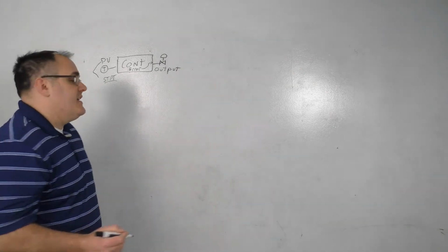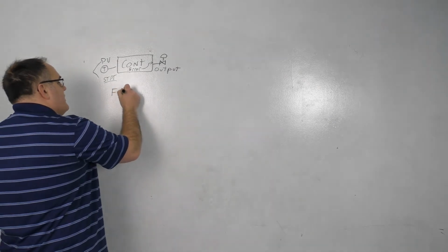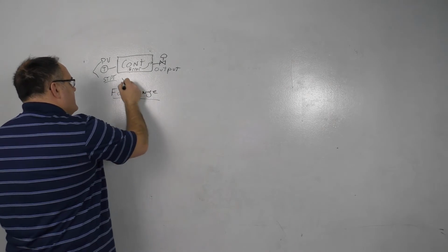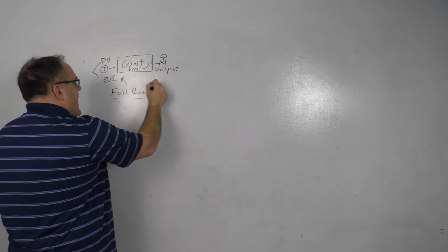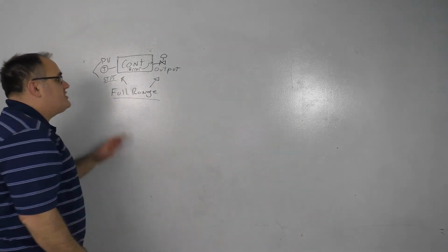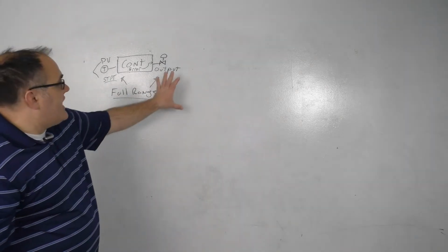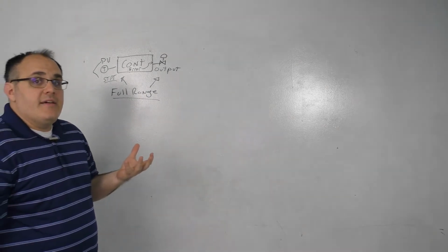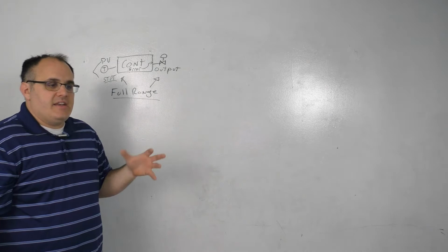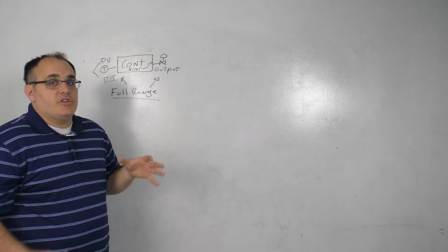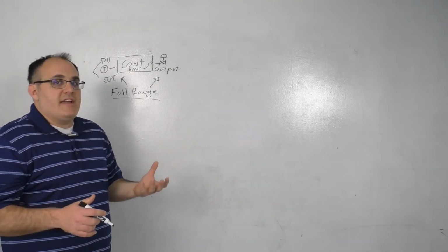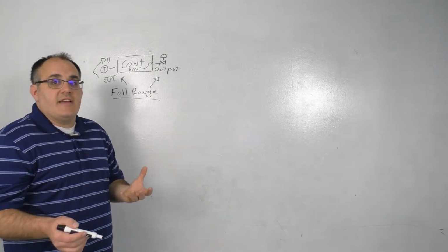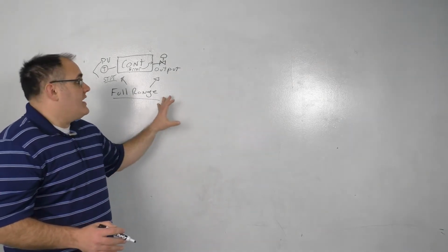And it's really important that we calibrate across the full range, okay? For both inputs that we're going to calibrate as well as for outputs that we're going to calibrate. So once you've got your inputs calibrated, then you need to calibrate your outputs. You need to make sure that if it's an actuator sitting on a valve stem, that it is properly seated on the valve stem so that when it's at 0% on the actuator, that is a true 0%. We want to make sure that we check those out.